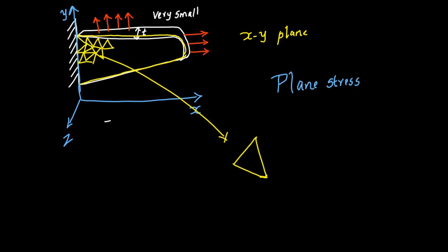Definitely, there should be more explanation of what the plane stress condition actually is, but no load is acting perpendicular to the xy plane, right? And the thickness is going to be very small compared to the other two dimensions. So the stress along the z direction is going to be very small. For all practicable purposes, we are going to ignore the stress values along the z direction without incurring any serious error in mathematics.